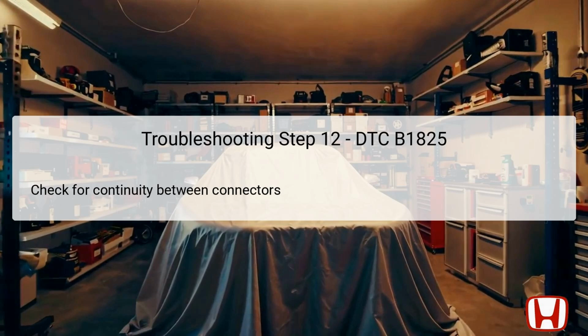If continuity is confirmed, the wiring and connections are intact, and the components are communicating effectively. If continuity fails, it often indicates that there may be a problem with either the wiring harness or the connectors. Ensuring continuity is essential for diagnosing issues in complex electrical systems.